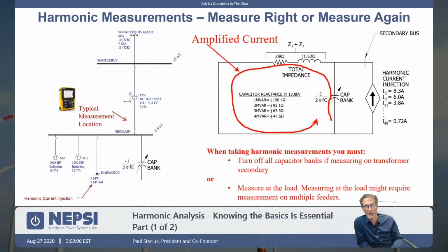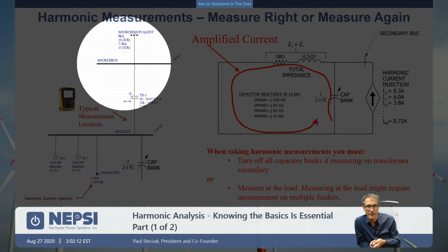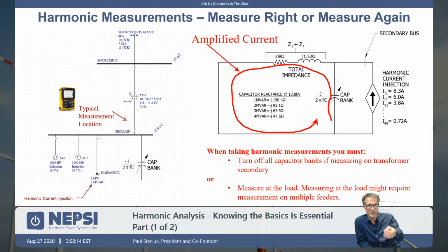And that actually leads to a very conservative result. The reason is that you have a voltage source out here in your model. The question is, what is the impedance behind that? How much current can it drive? And remember, during series resonance, it can appear as a short circuit. It's basically a tuned filter. The transformer impedance with the capacitor forms a filter from the transmission grid, and it could create a very high current draw.